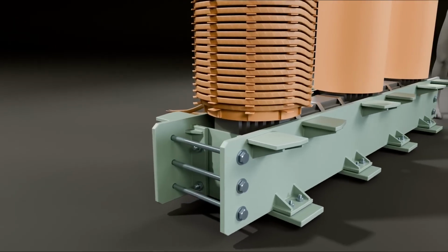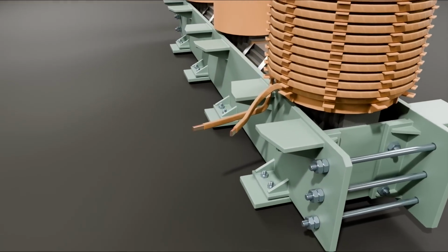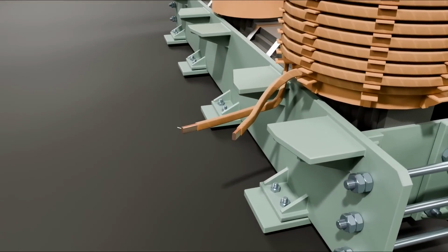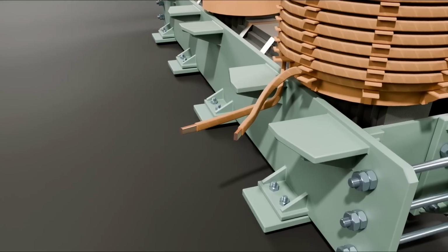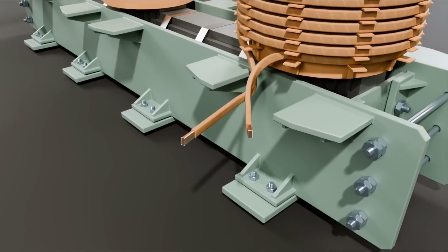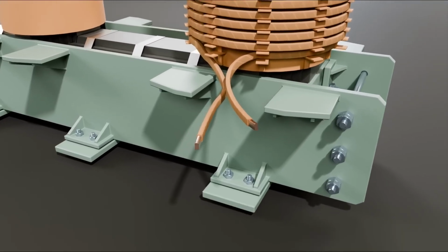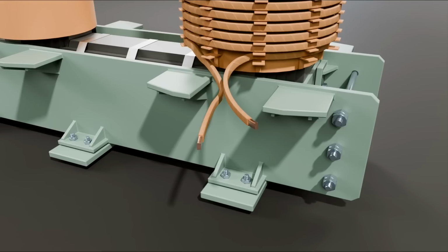Transformer windings are made of high-conductivity copper due to its excellent mechanical properties and high electrical conductivity, making it an ideal material for this application. For all transformers with ratings larger than a few kVA, rectangular section conductors are used instead of the normal round conductors. This is because windings with rectangular section conductors have a good space factor and high mechanical stability.